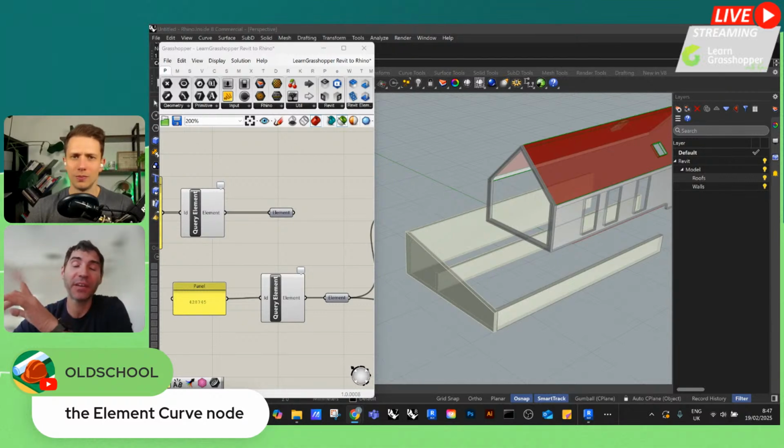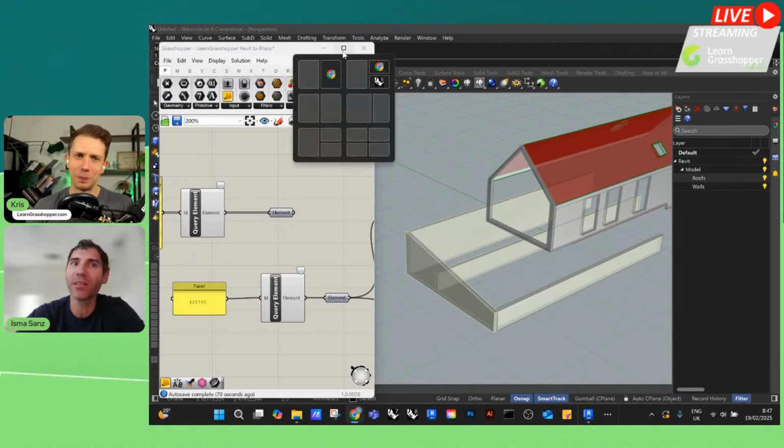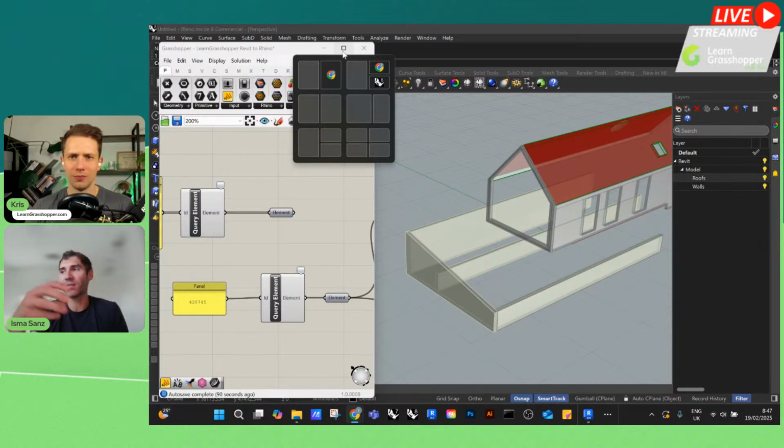If there's not a component to do that, and they have actually created so many components in Rhino.Inside that most likely there's one, you can always create a Python script if you know how to program and access the Revit API, and then get whatever you need. Because at the end of the day, all these objects behave like code, so you can extract the information from the different elements in Revit.